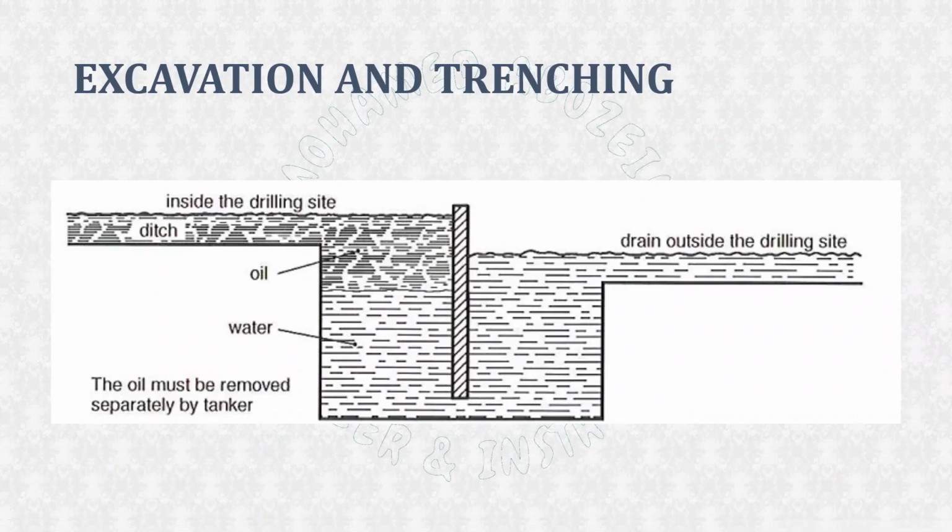Oil traps are made to provide a means for treating oil-contaminated water by skimming process. The skimming process depends on gravity segregation. Oil has less density than water, so oil tends to be on top of water. And by the use of oil-wet material, it can be easily removed.